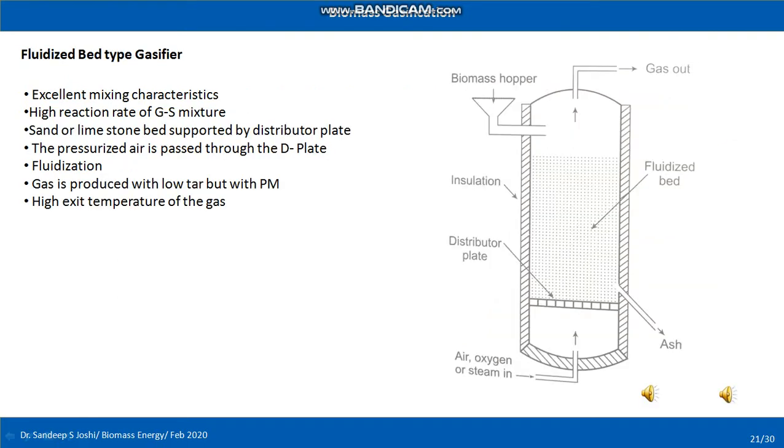Then this is one more type of gasifier that we called the fluidized bed type. A fluidized bed gasifier takes advantage of the excellent mixing characteristic and high reaction rate of the gas solid mixture. A simple fluidized bed gasifier is a chamber with a bed of inert particles such as sand or limestone supported by a distributor plate. You can see in this case there is the distributor plate, and this is the fluidized bed. This fluidized bed is simply fine limestone or sand particles.